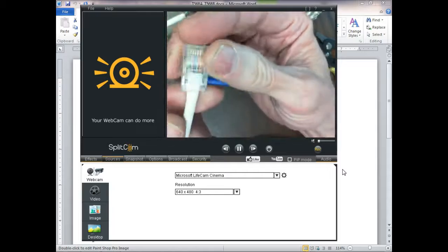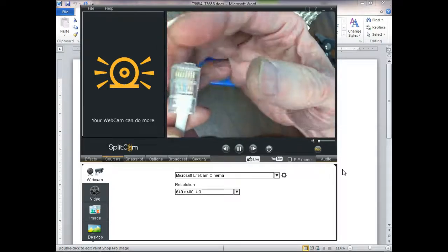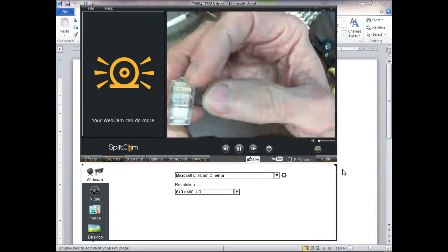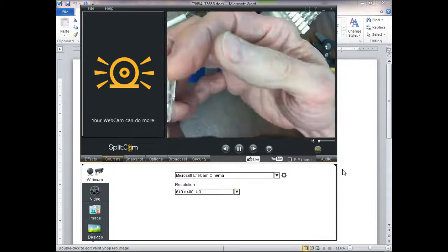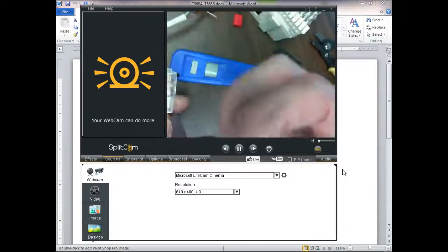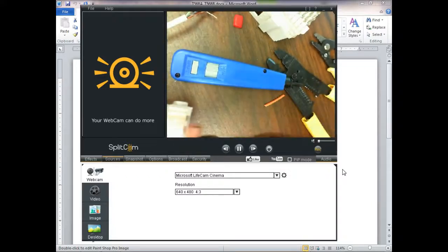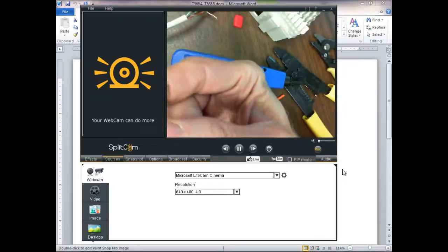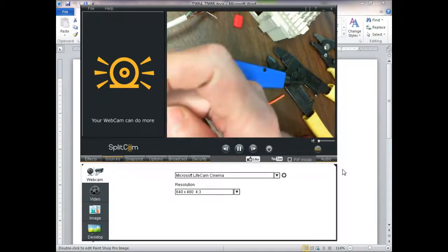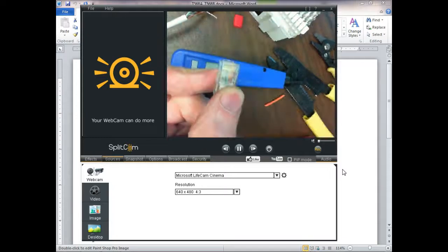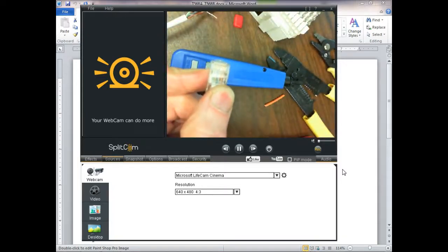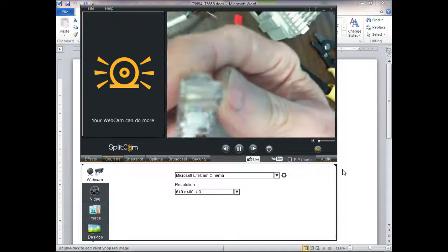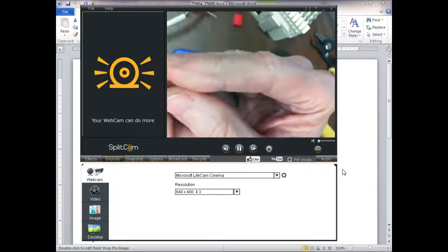These are crimp connectors. Which means what? That means you crimp them with a special crimp tool, right? When you get these things, and I'll pass it around, if you look at the blades out here, they actually protrude out. So they're actually out a little bit. And what you do is you don't strip these wires. I've seen people do that. What you do when you crimp it, it takes these guys and pushes them into the conductor and actually cuts through the insulation and makes your conduction that way, right? So you just strip the jacket in there.